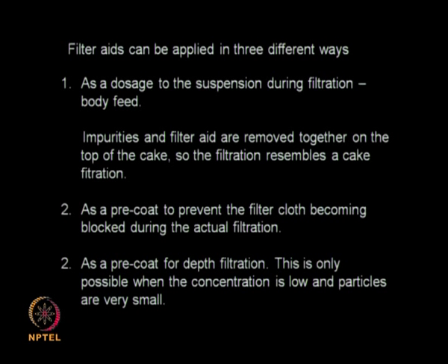The third approach is if you are using depth filtration, again you can use the filter aid as a pre-coat, but here you need to keep in mind that the particle size of the filter aid has to be small, so that they travel right down to the bottom of the filtration unit.